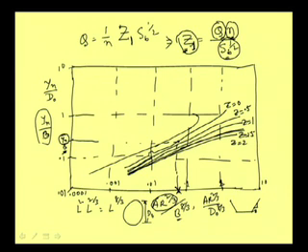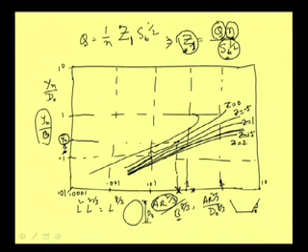If your z is, suppose, 1 or 1.5, then from the same point you will go to the corresponding curve, and you see the y n by b value. Now, the problem: suppose it is a circular channel, and your z1 value, I am talking about the section factor value, has come up to this much. Then you come to the circular curve. If it is a circular curve, you go there and find a value. For this point there is no problem.